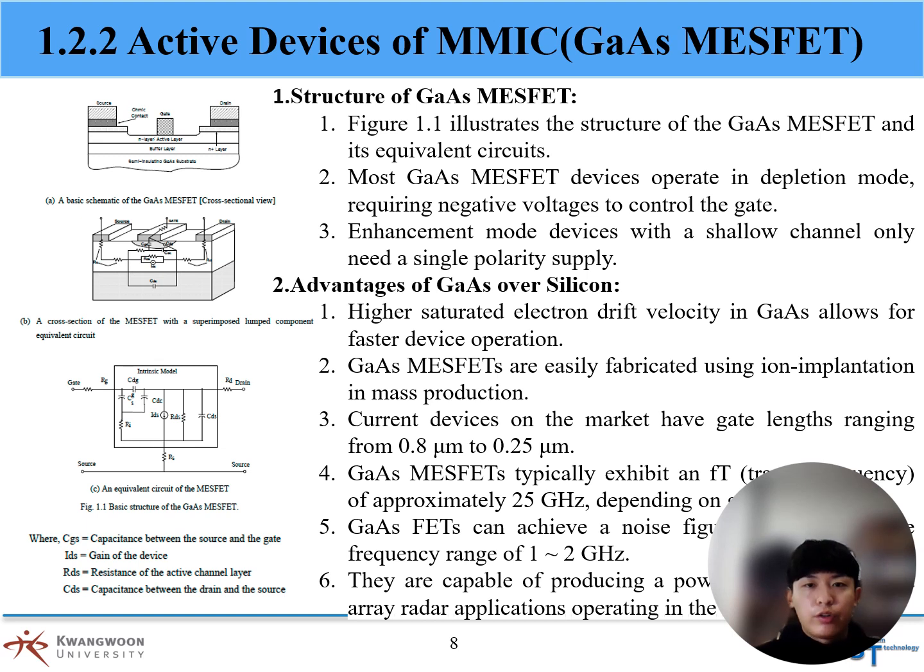A number of technologies have been developed for MMIC, including GaAs MESFET, GaAs HEMT, GaN HEMT, GaAs HBT, CBJT, SiGe HBT, and so on. The material choice for an MMIC application is dependent on the electron drift saturation velocity, mobility, and resistivity, among others. The main active devices for MMIC are explained briefly in the following.